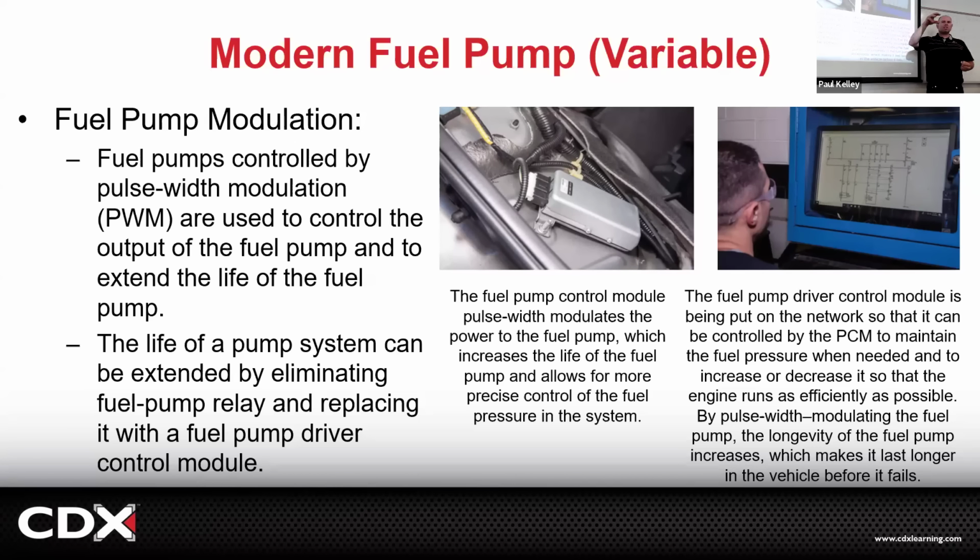If we have a fuel pressure sensor and we're targeting 50 PSI, and let's say we only have 40, do you know what we need to do to the pump? Turn it on a little bit more or speed it up. And then if we get to 60 PSI, be like, whoa, take a break, turn it off a little bit longer or slow it down, right? So we have modern fuel pumps that are not just on and off. They're speed up, slow down, pulsed on and off, through pulse width or duty cycle. And that's good.